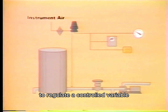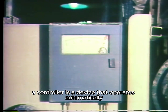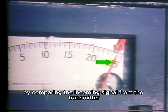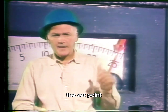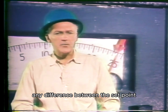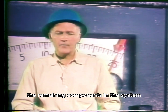To regulate a controlled variable, pneumatic systems use another type of instrument called a controller. A controller is a device that operates automatically by comparing the incoming signal from the transmitter to a predetermined set point. The set point in this case is the desired level in the tank. The controller computes any difference between the set point and the incoming signal and sends a corrective pneumatic signal to the remaining components in the system.